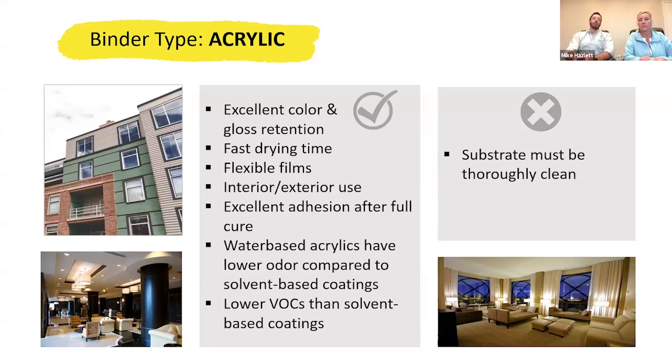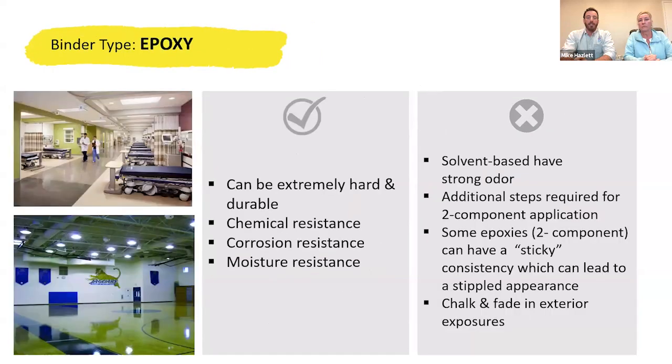And again, we're still meeting those low to zero VOCs. It's important to address with the acrylics that you want to make sure the substrates are still very clean and that the surface prep is done properly. So it's basically an increased, better version of your typical water bases. Epoxies get tricky. We deal a lot with this for floors, most commonly.